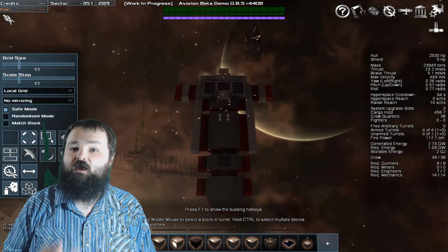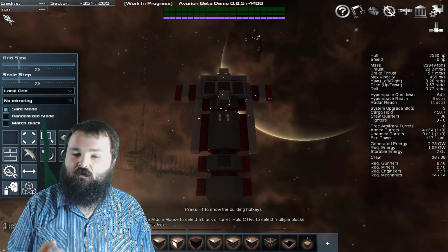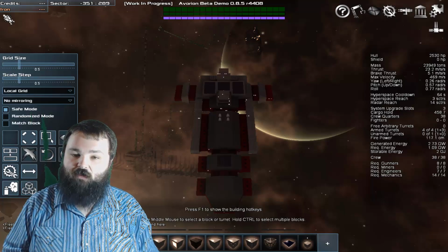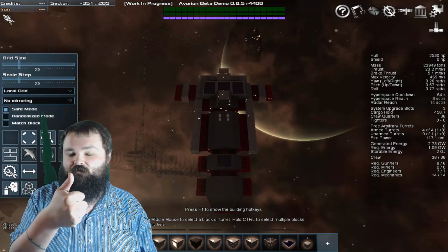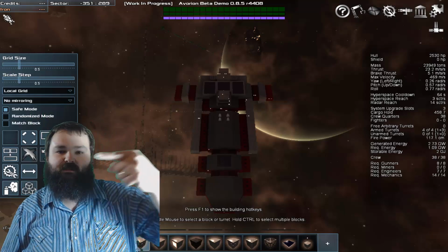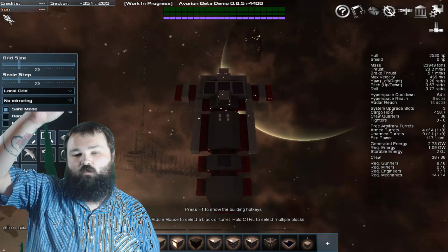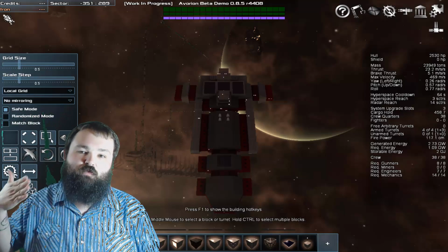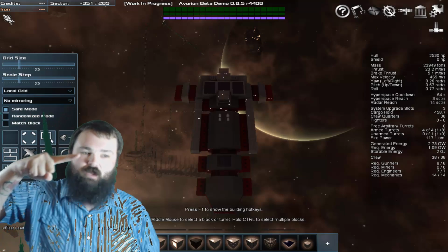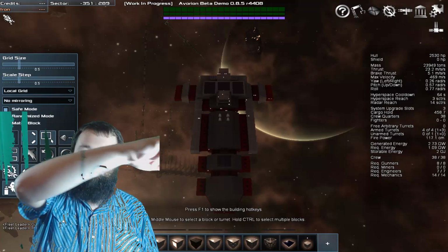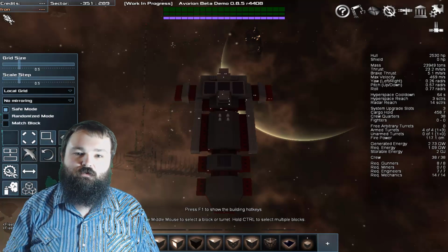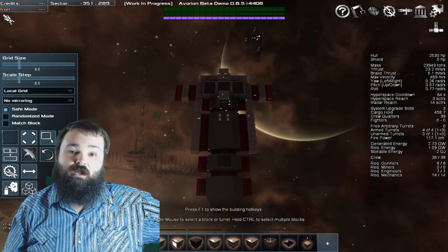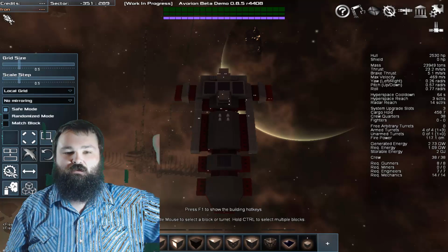When you're in space, 3 of those forces are negligible. You're obviously not going to have any lift because you're not going to have any air resistance giving your wings lift. There's going to be no air resistance providing drag, nor is there going to be weight due to gravity. So you only have thrust, and if you're only thrusting this way, how are you going to stop? You're just going to keep going that way forever due to Newton's first law. So what you have to do is you have to create brake thrust, or thrust facing the other direction.